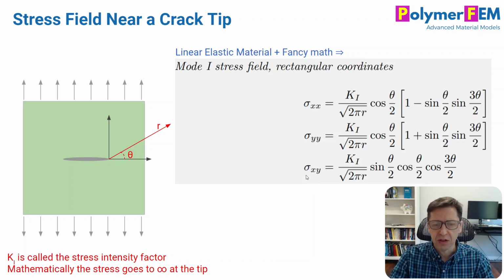The stress in this case is 3 stress components. It's a 2D problem, so sigma xx, yy, and xy, and they're given by these equations. It's pretty interesting that you can actually perform this calculation. That's something that people back in the day did a lot of work on, because computers weren't invented really back then. So they were very smart and they came up with these equations for how the stress depends on the angle and also the distance from the tip.